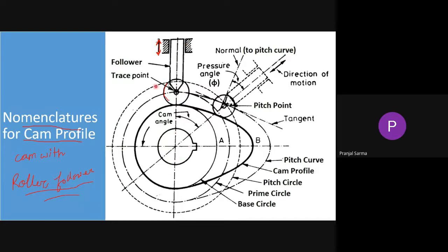Okay, now from this particular look, can anyone tell me whether this configuration of cam and follower is the offset type, or inline, or radial type? Yes, anyone? Sir, radial maybe. Yes, not maybe, it's radial, or inline type, because you can see the axis of movement of the follower passes through the center of rotation of the cam itself. There is no eccentricity in between.